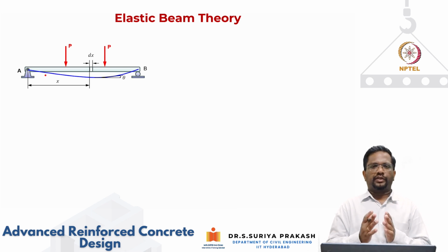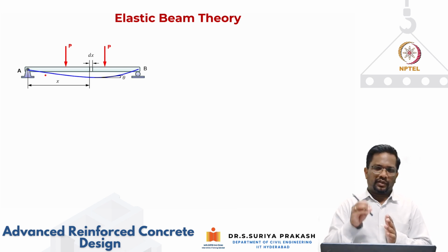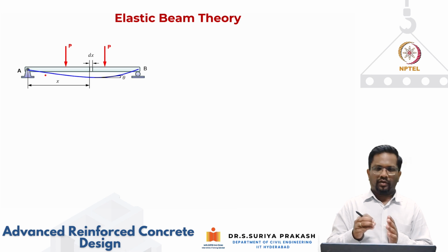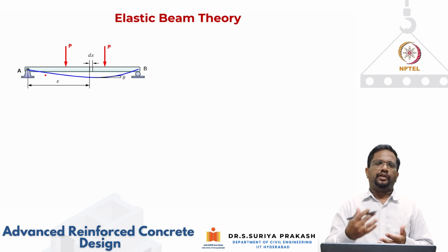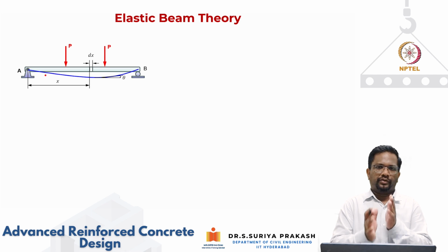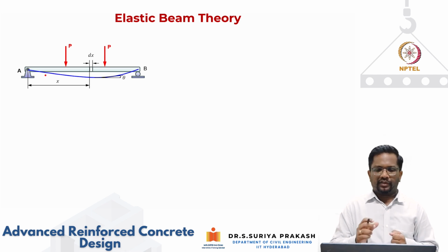that particular cross section is behaving with the certain reinforcement and concrete strength that we have assumed. So to compare the different sections, it is easy for us to compare, so that we can compare apples to apples. So that is the reason we do moment curvature analysis.